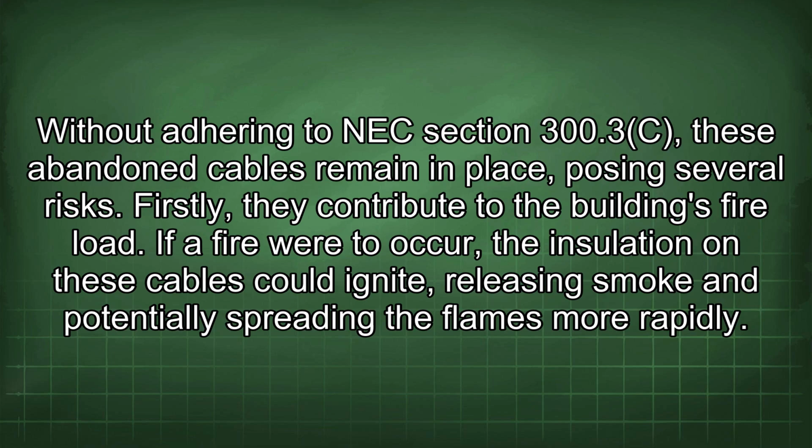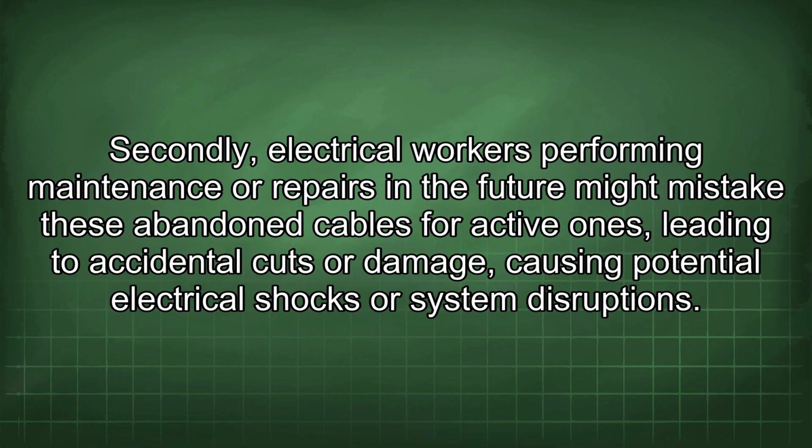If a fire were to occur, the insulation on these cables could ignite, releasing smoke and potentially spreading the flames more rapidly. Secondly, electrical workers performing maintenance or repairs in the future might mistake these abandoned cables for active ones, leading to accidental cuts or damage, causing potential electrical shocks or system disruptions.